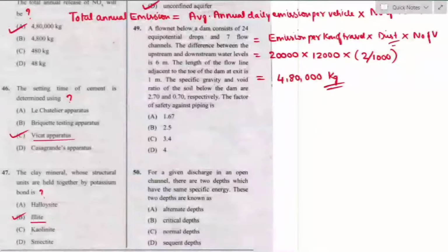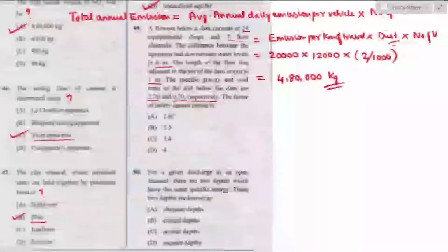Question number 49. A flow net below a dam consists of 24 equipotential drops and 7 flow channels. The difference between the upstream and downstream water levels is 6 meter. The length of the flow line adjacent to the toe of the dam at exit is 1 meter. The specific gravity and void ratio of the soil below the dam are 2.7 and 0.7 respectively. The factor of safety against piping is...